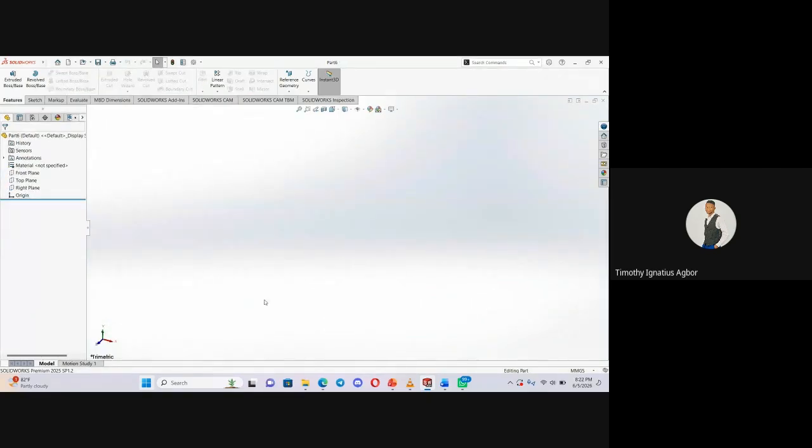And I said, when you want to use a revolve boss is when you are trying to create a shape that you only have the cross section of. Probably a symmetric shape. So you can use that cross section to create that shape without having to have the full dimension of the shape. And an example of such shape is our shaft.